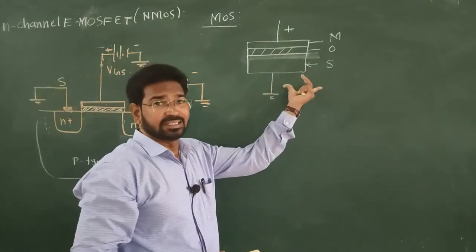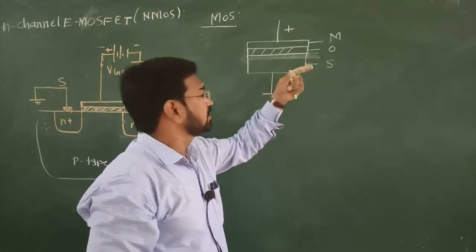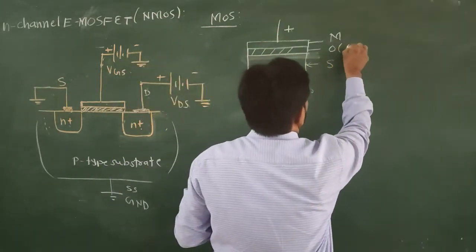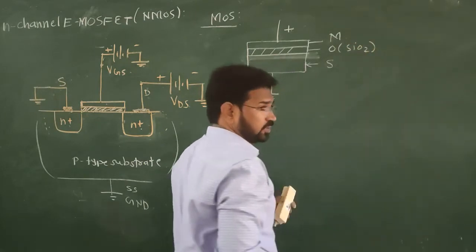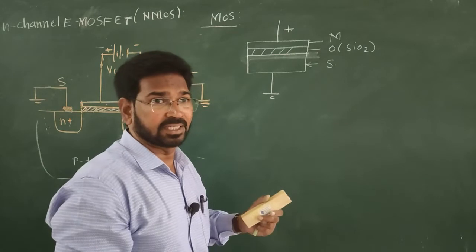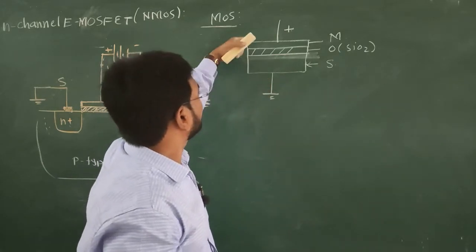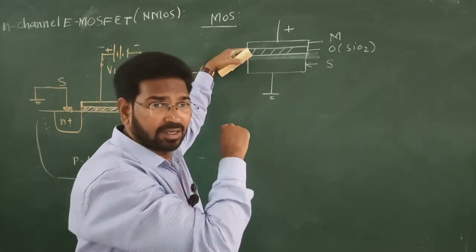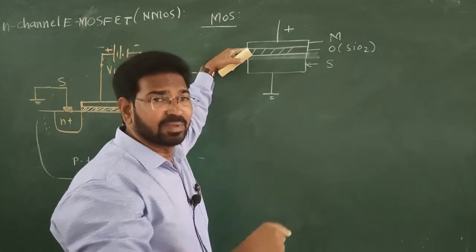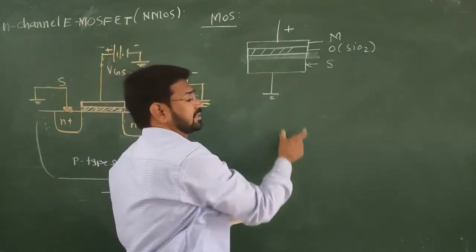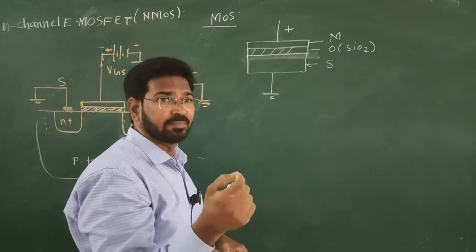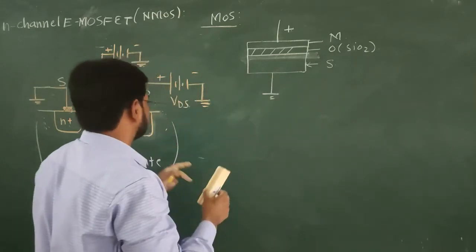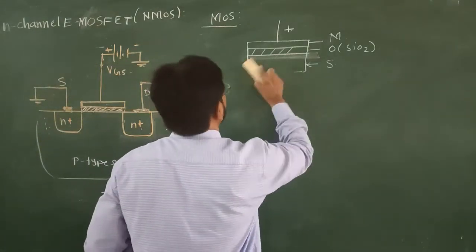See, this resembles a capacitor. Between two conducting plates, there is one dielectric material. So, silicon dioxide is used and it is a dielectric material. It has permittivity and these are very thin layers. Metal is also thin. The oxide layer is very thin, and thickness is measured in angstrom. The semiconductor is the substrate material having some conductivity. As it is slightly doped, it has holes and electrons. Remember these points so that we can understand how the current flows in the MOS transistor.